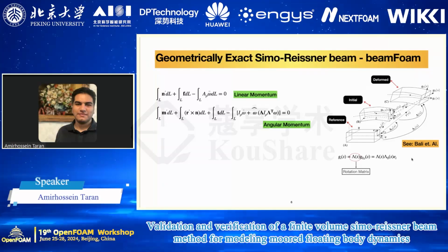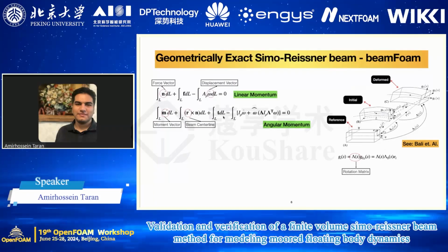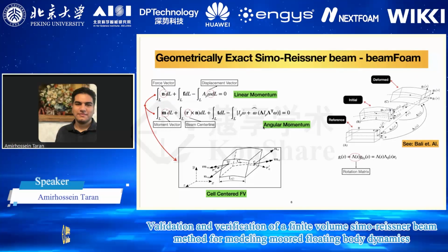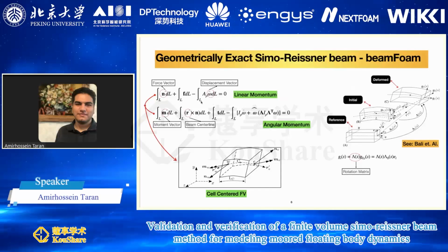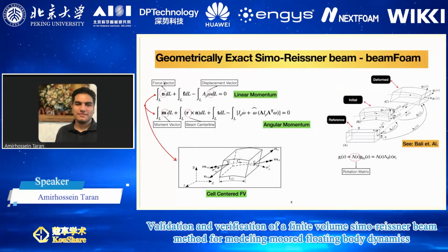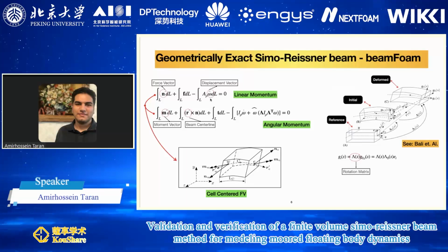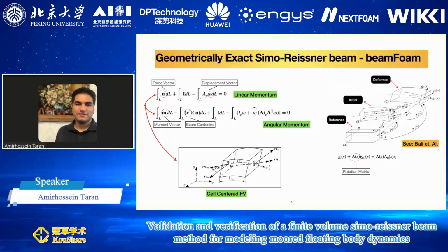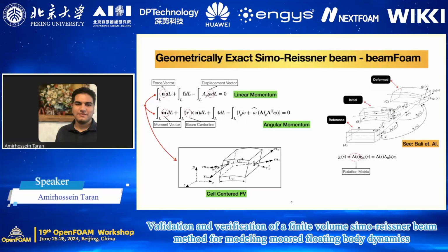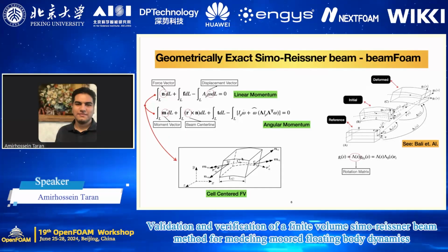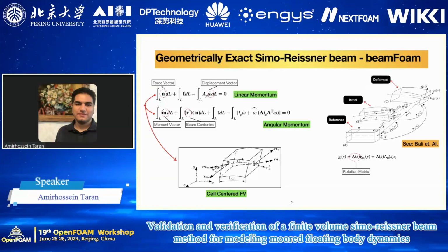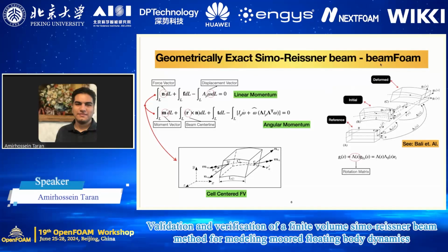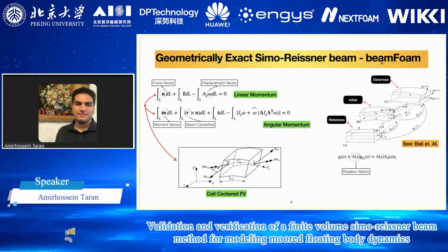They discretized the integral form of the equations into a cell-centered finite volume. These equations are linear momentum and angular momentum, followed by two constitutive relations. You can solve for any force vector based on the displacement, and you can discretize these equations on a finite volume. Then you can easily code it within OpenFOAM. So we have this approach implemented in OpenFOAM called BeamFOAM, which is just a beam simulator.